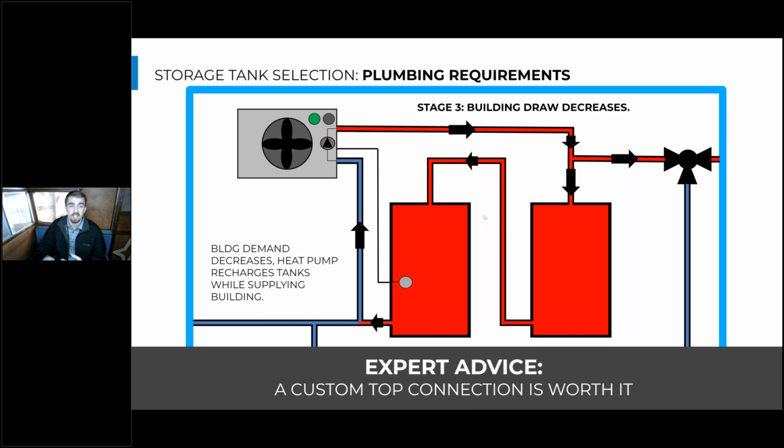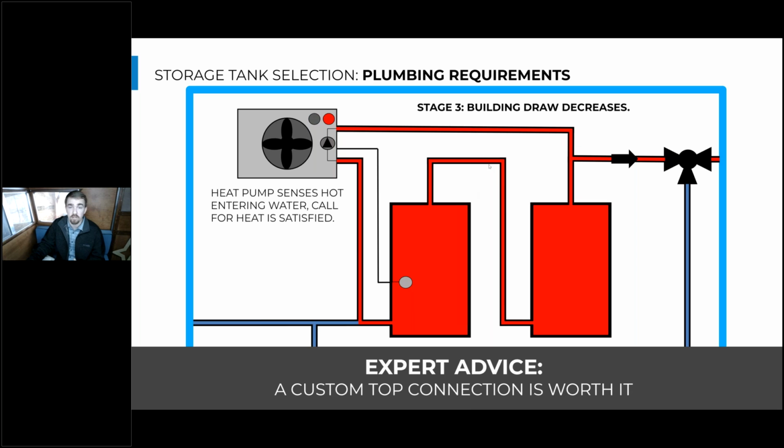And then as people are done showering or stop using as much hot water, now the heat pump's supplying more water than the building requires, and it can recharge that storage. And then once the storage is totally recharged, the heat pump sees that warm water coming back, meaning that hot water's made it all the way to the bottom of the tank, and now it's going to shut off and know that the load is satisfied.